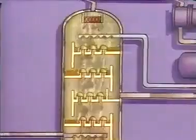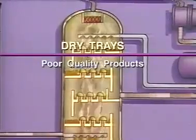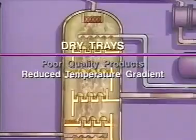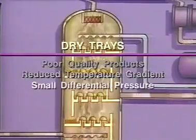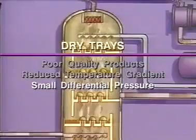You can identify a tower with dry trays by the following characteristics. First, the tower will produce poor quality products because no fractionation can occur on a tray without liquid. Second, the temperature on a series of trays without liquid will be about the same, so the temperature gradient in this section of the tower is very reduced. And third, there will be a small differential pressure through a series of dry trays because there is no liquid to resist the flow of vapors.